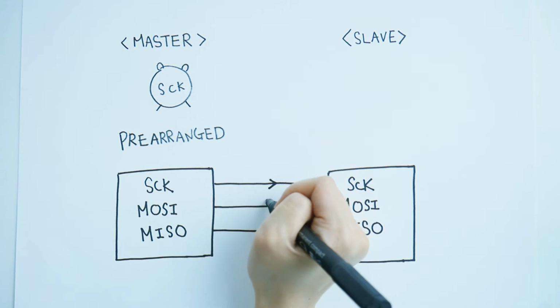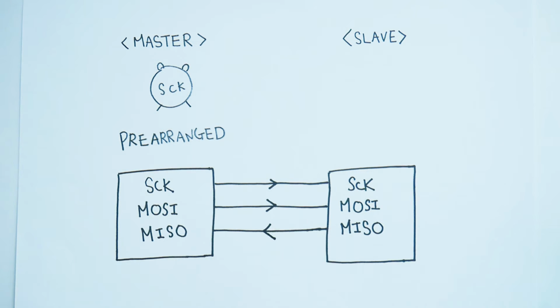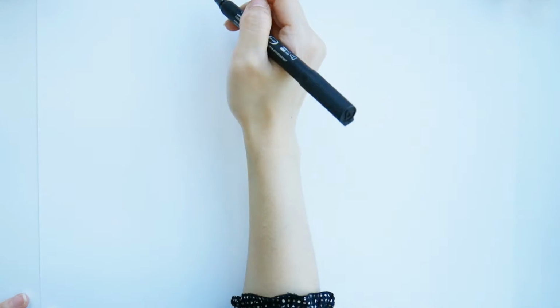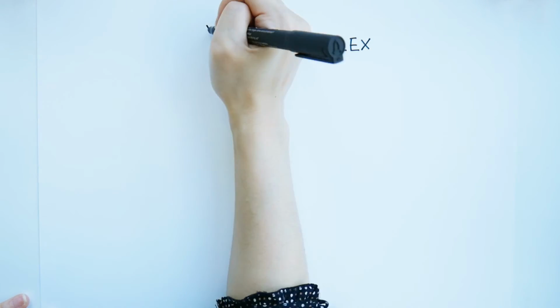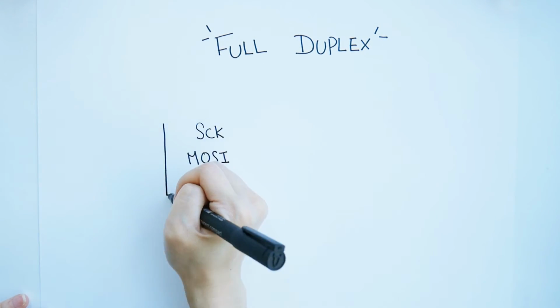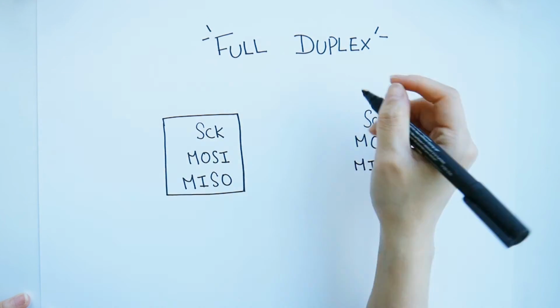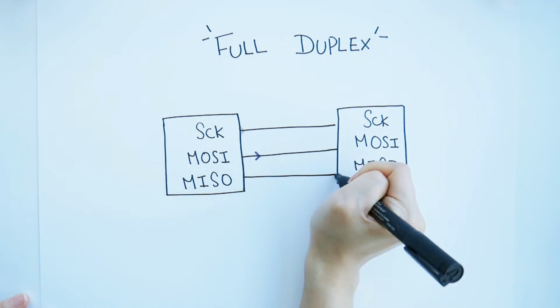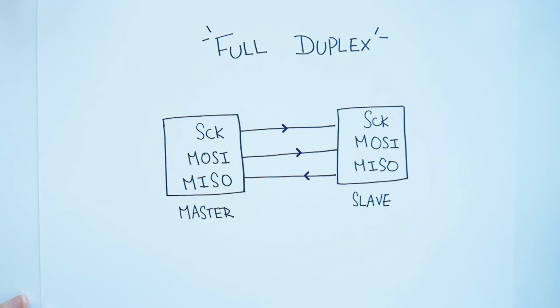Remember, SPI has a data exchange mechanism. Even though it is a data write operation, which means that there is no data transmission from any slaves, the master always receives data. It should be ignored in this case. SPI is full duplex, which means that it has separate send and receive lines. So in certain situations, you can transmit and receive data at the same time.